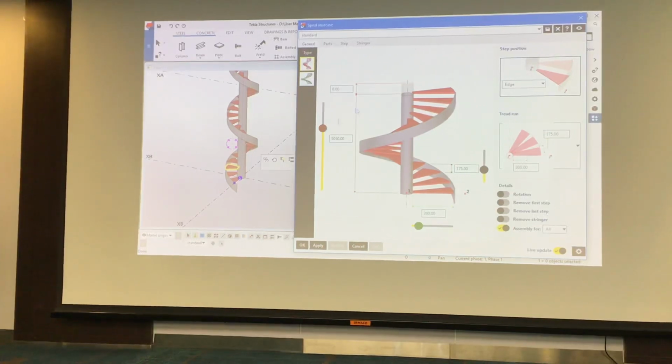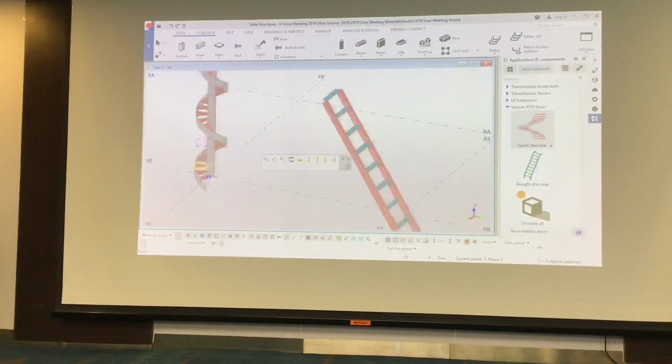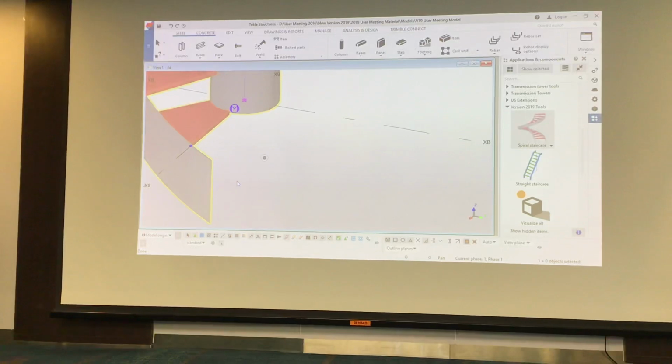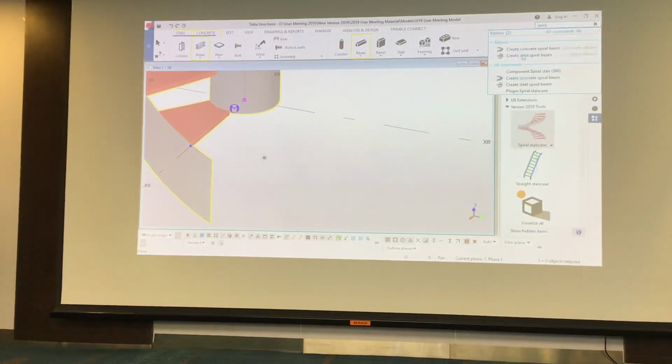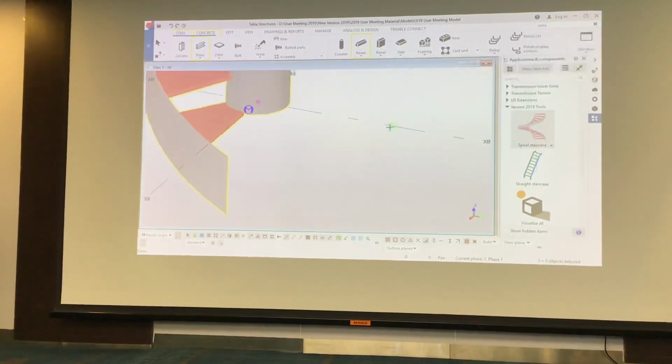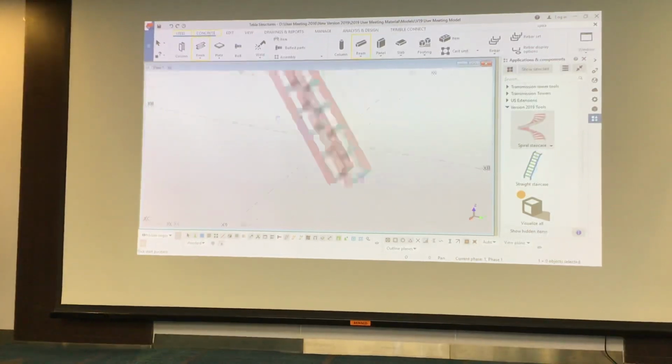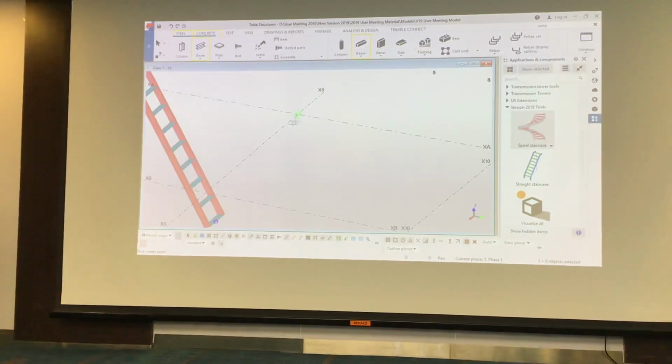So some really nice. These spirals, if you look, are correct. So they're like proper plates that spiral all the way up. They're not made from segments, it's one continuous plate. And that actually is something else. If you do a search for spiral, you can say create a steel spiral beam. So steel spiral beam, you can draw, let's say, from this point here.